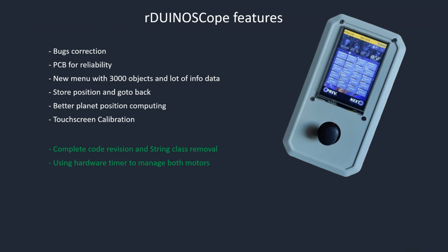With the ASCOM implementation, it was necessary to have hardware management of the motors because it caused motor cutout when ASCOM communicated through the serial port. Once this migration was done, it resolved another bug: the freeze during the go-to phase when using the Bluetooth. So the motors are now completely independent. There is no longer a CPU load to run them and the system is now smoother. There are no more interruptions due to the use of ASCOM, Bluetooth or anything else related to the interface.